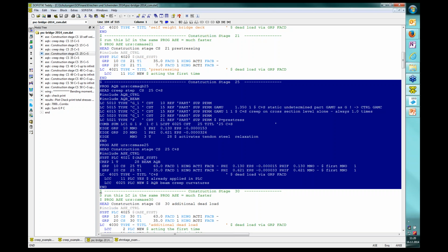Now what's going to happen is, in case our concrete wants to shrink, the concrete starts shrinking, but the steel rebars inside the concrete work against the shrinking process. That means that inside our construction we create stresses based on the shrinkage effect of the concrete, which has a resistance by the rebar steel, and these stresses are caused only internally with no loads from outside. So we call them eigenstresses.